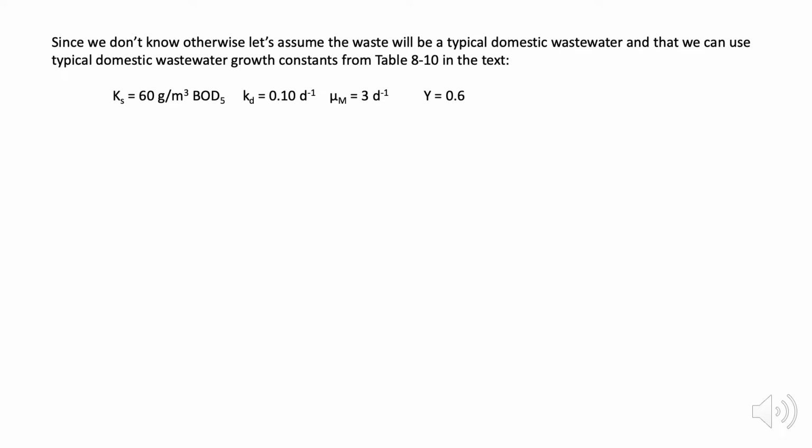Okay, so we don't have any wastewater as we begin this test, so we can't go and test it and determine what the growth parameters are for this wastewater. But we assume that it's going to be just a typical domestic wastewater, and that means that we can use just the typical wastewater growth constants for a domestic wastewater.